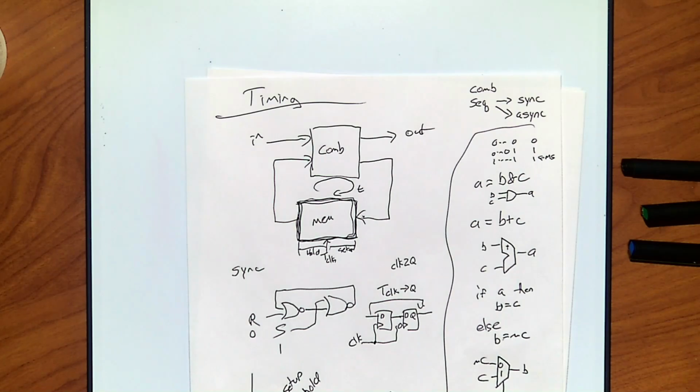So in terms of your clock, think of light leaving those tubes at the top and hitting the floor. We've got maybe 10 feet? So it's 30 cycles of your clock for light to go from the bulb to the floor. It's kind of shocking if you think about it, right? Because we don't realize timing really matters. Timing all these wires is non-trivial, okay?